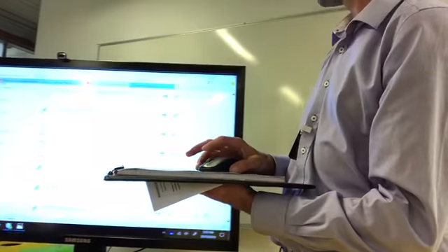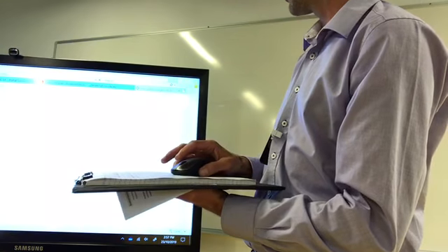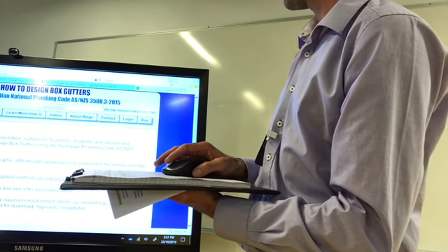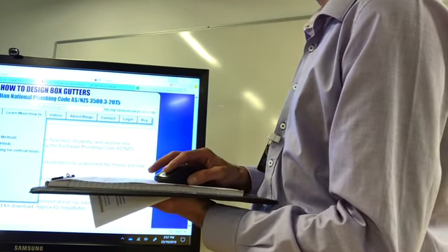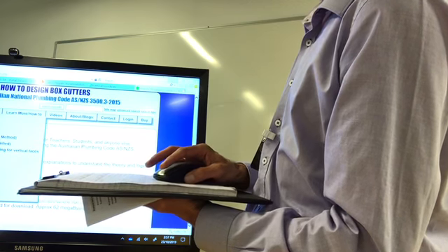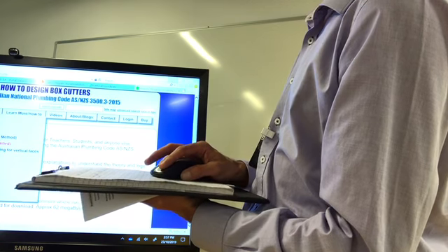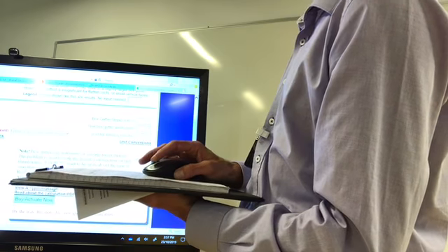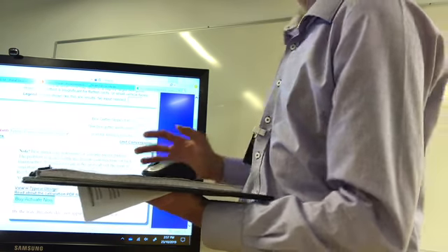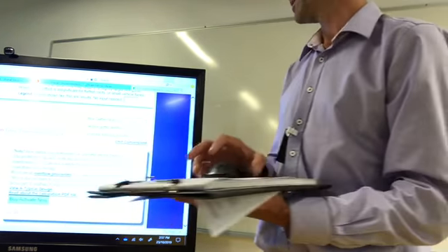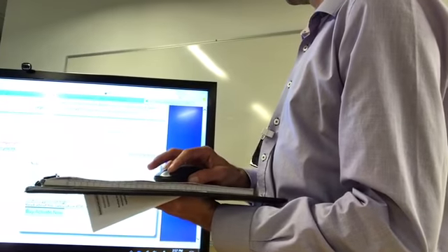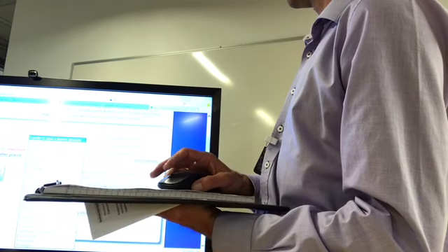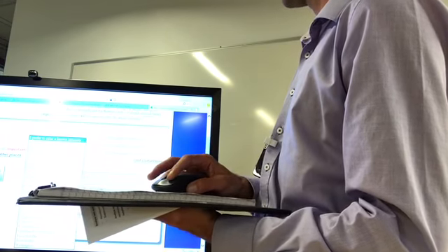So with that box gutter, how do we go? We go to more calculators. We go to box gutter to rain head, simplified. And in going through that, if you remember your 124, you can pop that straight in there. Otherwise, you can choose your location as well.